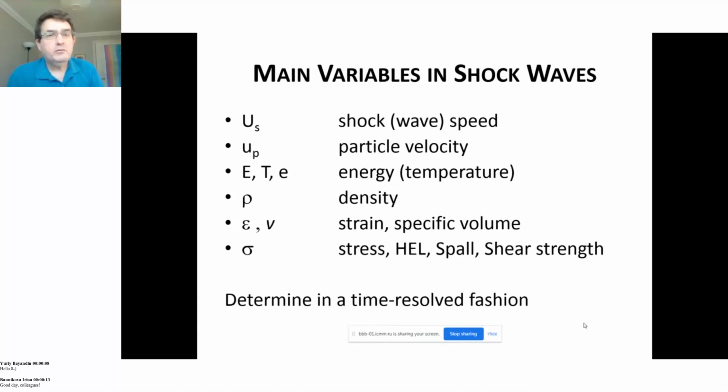Normally in the laboratory, we're looking at about 20% compression. The limit, according to the literature, is when you push the atoms towards their closest spacing, and on average, that represents a compression by a factor of 2, so 50% compression.